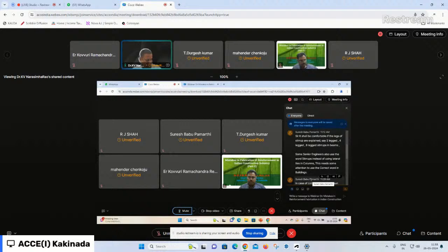Being a lintel with a limited depth, say 8 inches or 6 inches, the development length requirement of the main steel will necessitate the steel to be looped into a rectangular stirrup-like fashion. That is, it's better to have, suppose we are using some 8 bar in the sunshade.